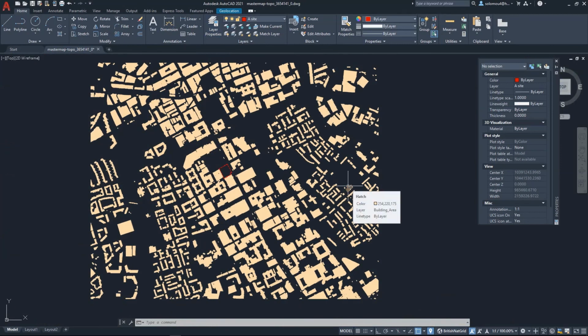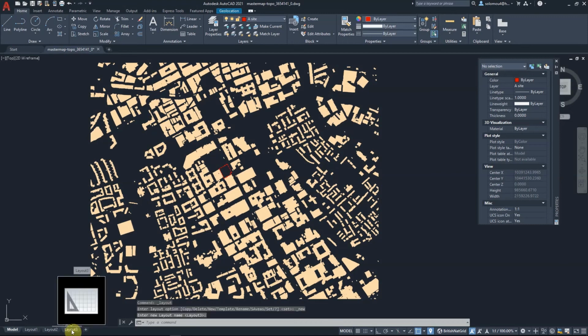Now when we looked at Digimaps, you can download a specific aspect of it like this. So how do we get this to be a specific scale and export it? Well, that requires us to work with our layouts down here. We have to create a layout. So now we have our drawing, we've set it up. We need to create a new layout. In order to do that, we go down here and press on the plus here. Perfect. And we created layout 3.